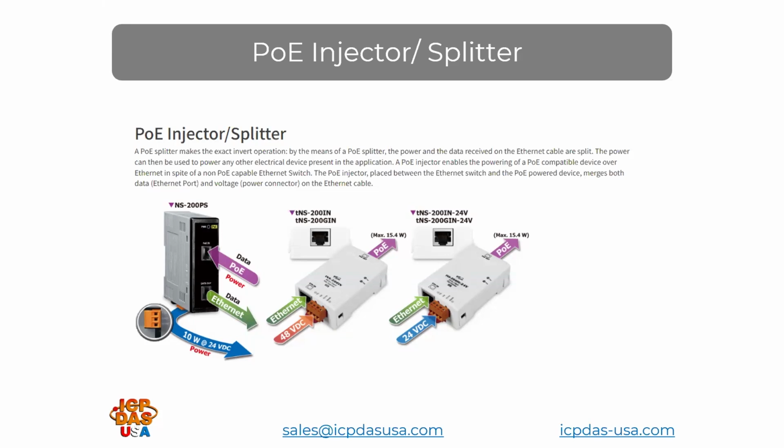This is used for like a single sensor or a single PoE device that you need to power in an area. Maybe, for instance, you're adding an IP camera and you want to simplify the wiring, so you just use a PoE injector to power that one camera, and you save the money of purchasing a PoE switch, which costs a little bit more, but it just saves you money because you really only need one PoE connection.